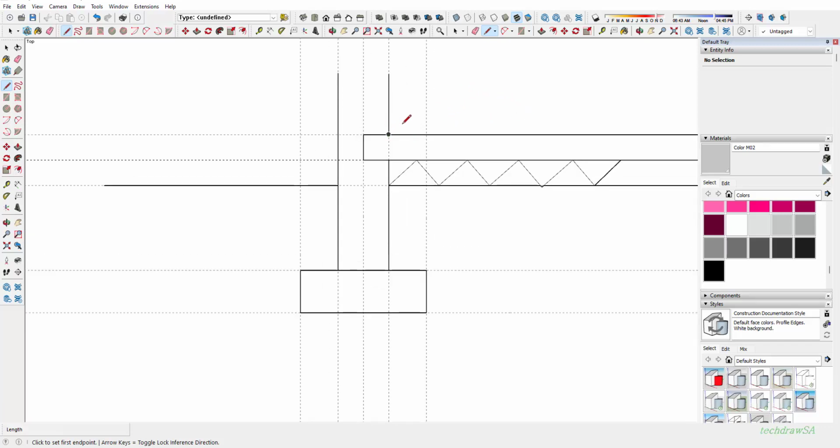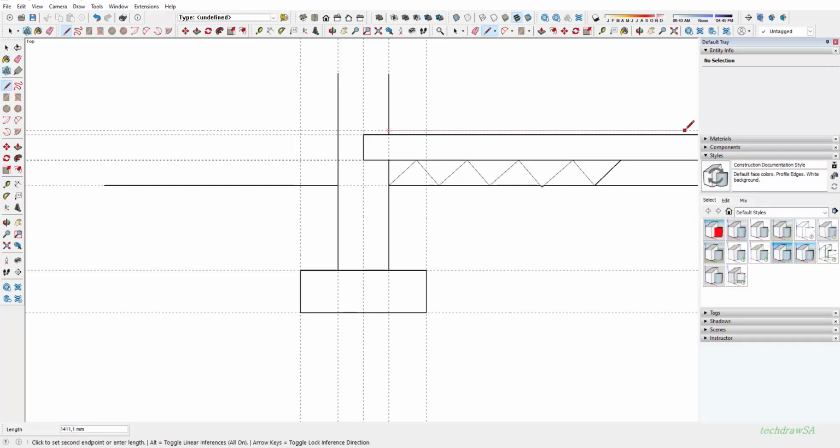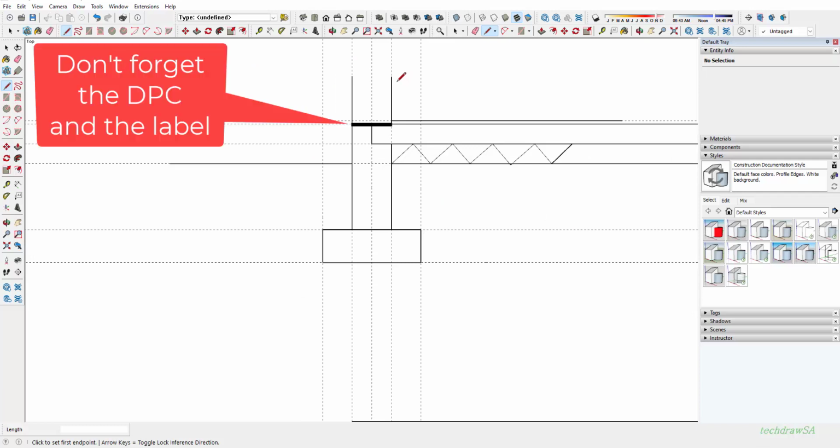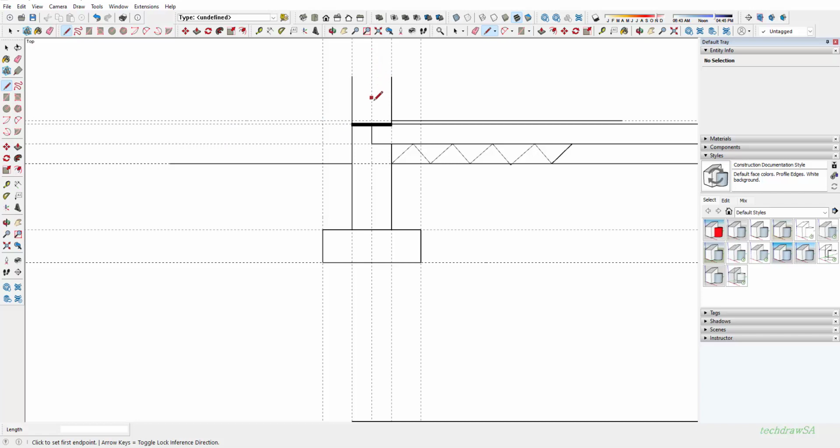Just make sure if there is a screed that is required. So if we say that you have a screed that you need to draw in, let's say it was 20 millimeters or whatever, depending on the scale that you use. So you obviously won't see that if it is a 1:50 scale, but let's just pretend we asked you to draw that in and you can then see the screed. So then you would have had that 20 millimeter screed or whatever measurements was given to you in your question. So then obviously you would have continued with, if there was a door, you would have drawn the door here, obviously starting from the FFL. If there was a window, you would draw the window there, and so on.